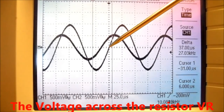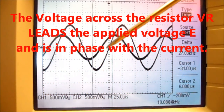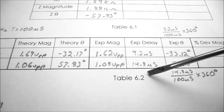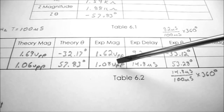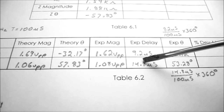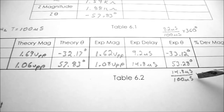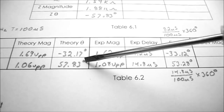I just want to remind you that when it's on this side of my applied voltage, it's plus. So this is a positive phase angle. So in table 6.2, I've recorded my VR experimental magnitude is 1.08 volts peak to peak, and my experimental delay for VR was 14.8 microseconds. And using the formula I used before, 14.8 microseconds divided by 100 microseconds times 360 degrees equals 53.28 degrees, which is close to my 57.83 degrees.